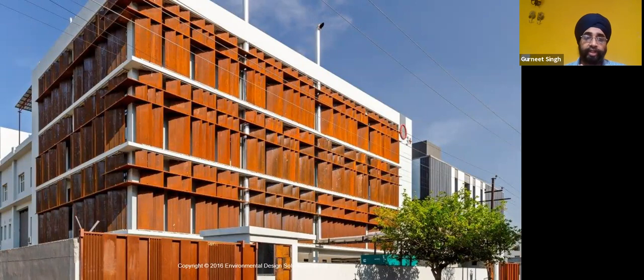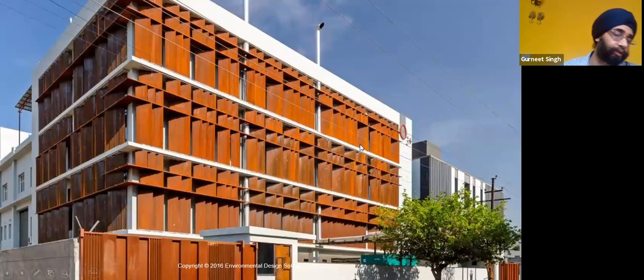The other benefit of shading is that besides radiant and glare control, it also helps in reduction of your cooling load, as the solar gain inside the building is now zero. So over here, there were zero solar gains. If we hadn't done shading, there would have been some solar gains coming into the building, contributing to the cooling load.